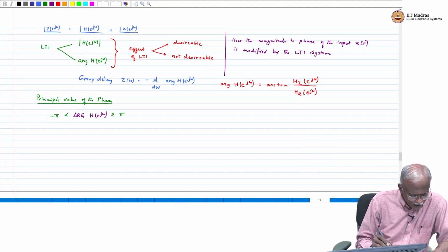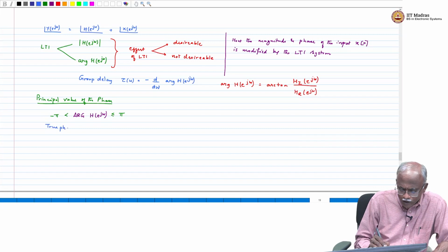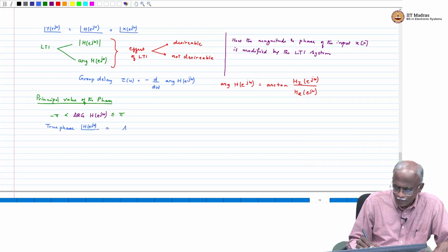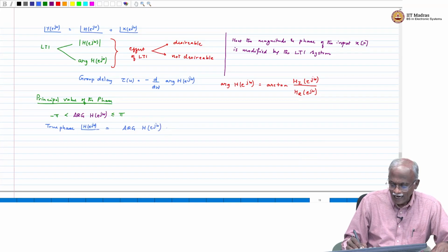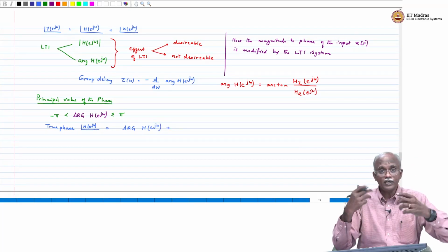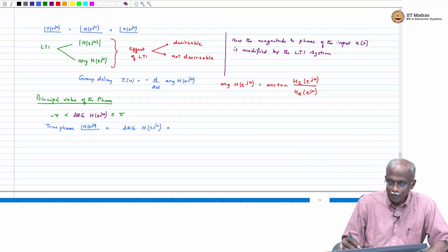So if I were to ask what is the true phase of H_e(j omega), can we get that? Yes, we can get it. It will be equal to the principal value of H_e(j omega) at each frequency, plus a correction. Remember, this wraparound can happen at any frequency. You may have to add or subtract multiples of 2 pi.